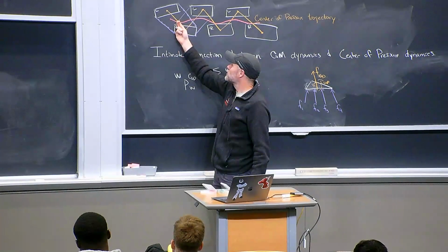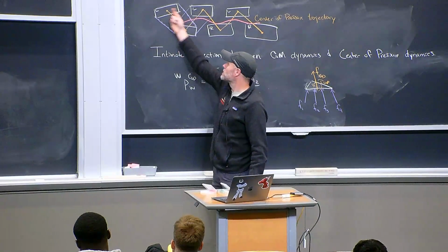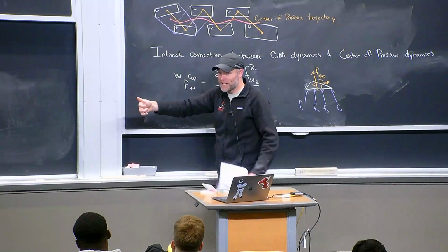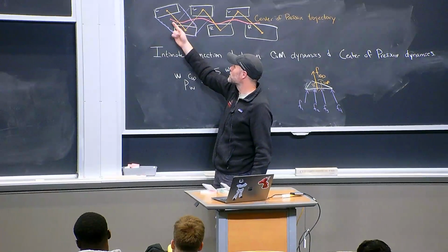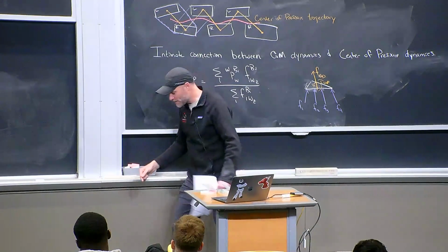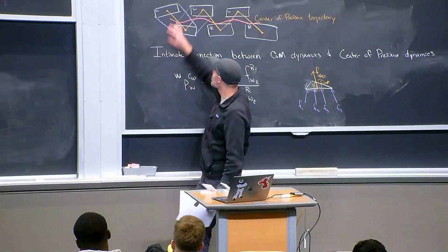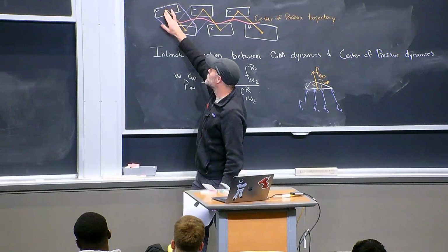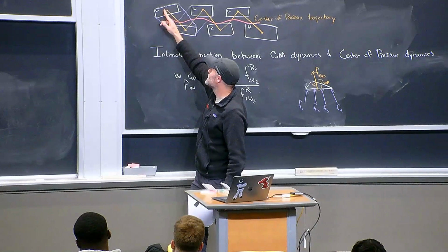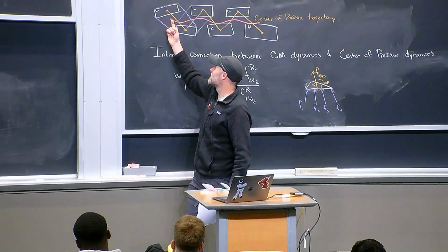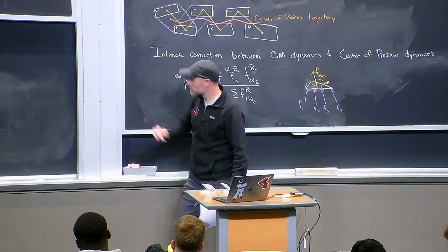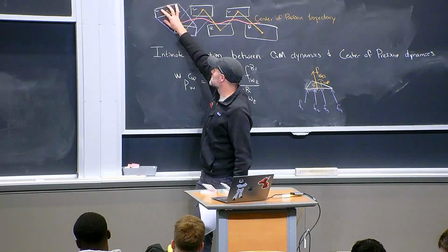If the center of pressure is completely inside this support, then you also know that you cannot be tipping over. Your foot cannot be tipping over. So first of all, when 2 feet are on the ground, I can move around back and forth as long as my force doesn't go to the edge of the foot. If my center of pressure is inside, the average force is inside there, then I must have some amount of forces on this side and this side that are compensating. It's only if my center of pressure gets exactly to the edge that I tip over.